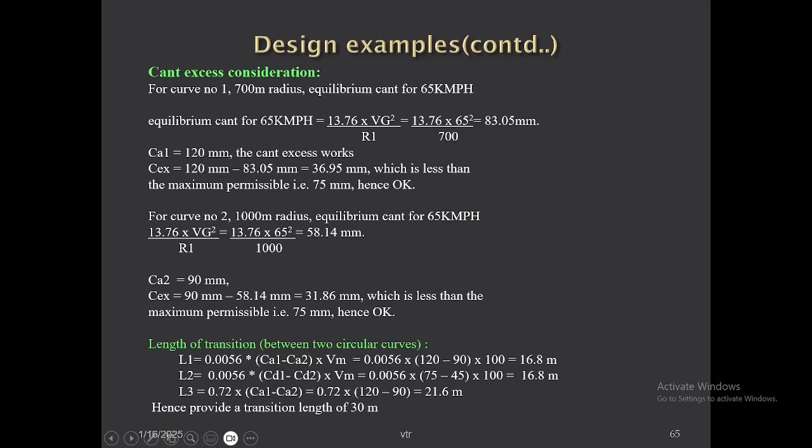Otherwise, as usual, you can calculate the superelevation for the first, normal curve. If there are no restrictions, you can directly use these three equations to find the length of transition. Here we have been asked to find the minimum length, so we are optimizing. That is the only tricky part here. Now let's go to the next example.